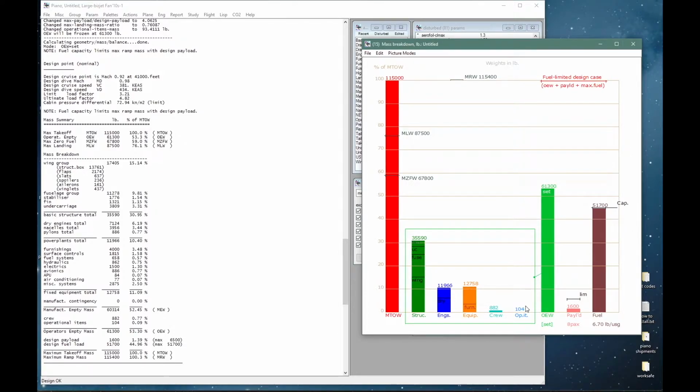This is not necessarily an indication of great accuracy in weight estimation, however. The balance between structure and furnishings weight is not known. We only have the manufacturer's expectation of OEW. For example, I did not apply any weight factors on the structural components. It could be that the composite wing is lighter and furnishings are heavier, or perhaps that Dassault chose to focus more on the aerodynamic benefits of thinner wings and less on the weight reduction.